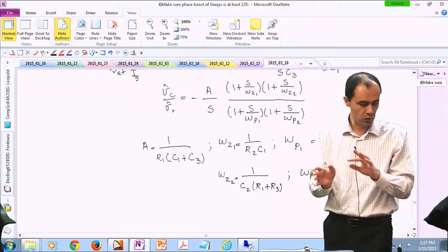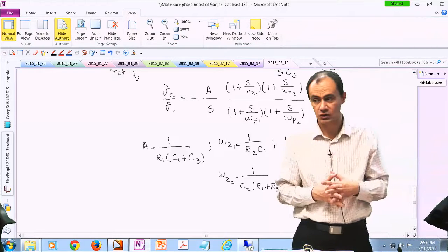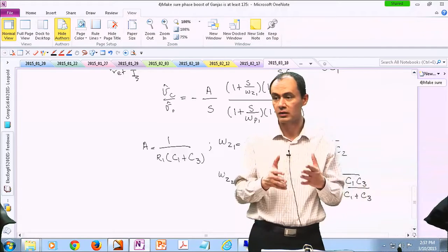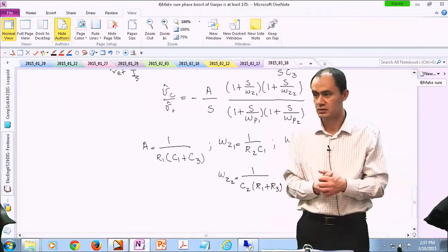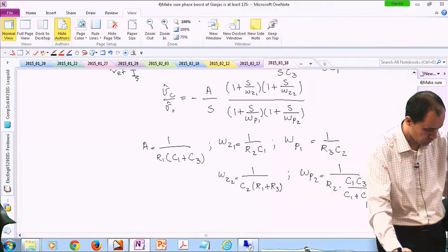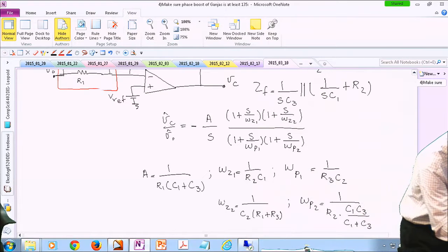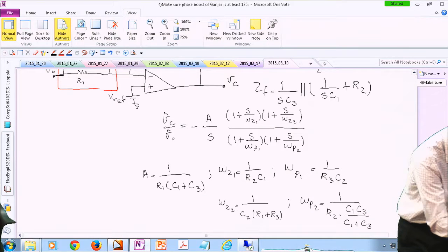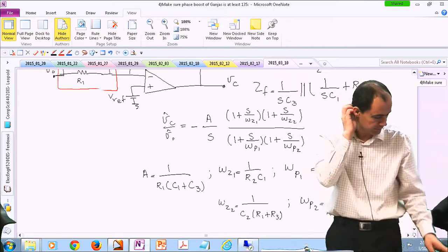So there is not a one-on-one kind of a match, so you still have extra degrees of freedom in determining the exact numerical value for R1, R2, R3, and C1 and C2 and things like that, okay? So this is what the network should look like. And again, as I said, don't worry about this negative sign. We actually need this negative sign because we're looking at the negative loop anyway, negative feedback.